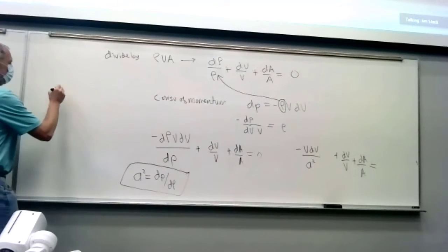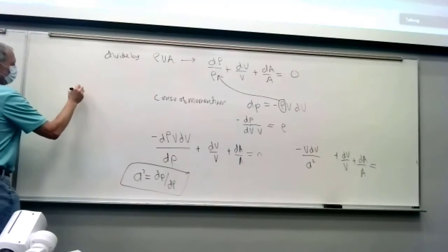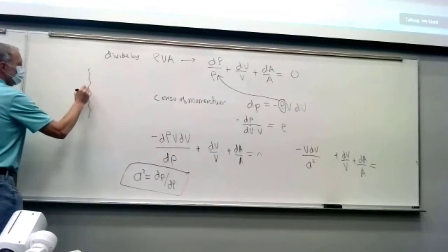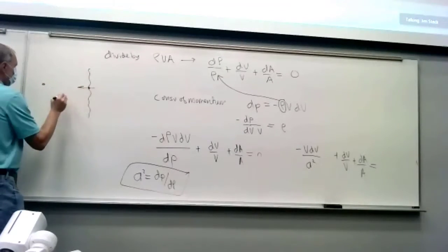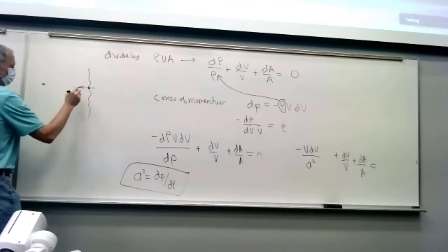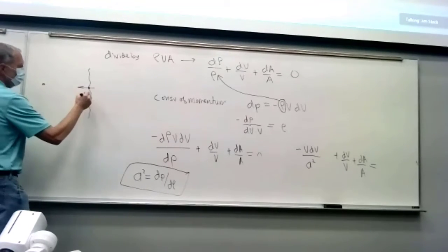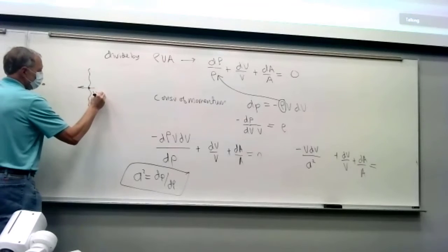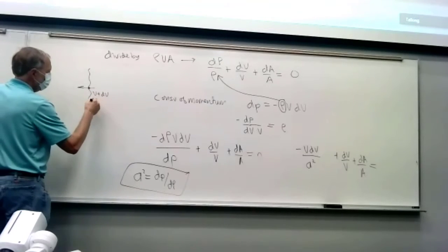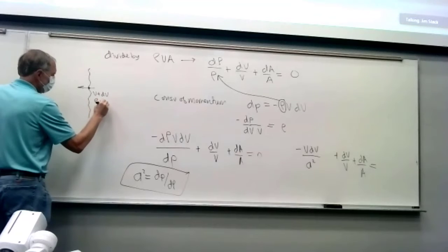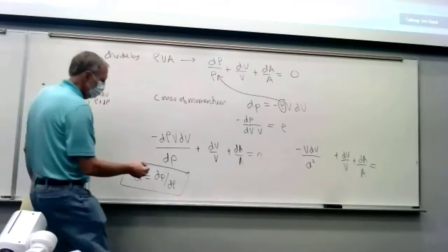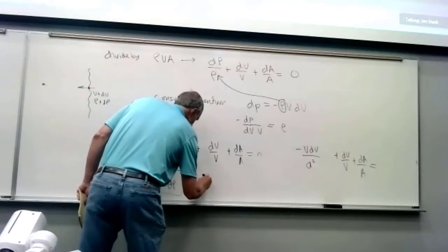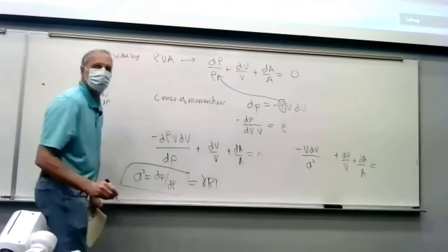Yeah, remember we looked at an acoustic wave moving through the air, and we tracked the flow as it went past a point, and we applied all of the equations in motion, like v plus dv, rho plus d rho. Did a bunch of algebra, and we found out that the speed of sound is given by that. And then we substituted into this to find out that it's equal to gamma RT from the ideal gas.